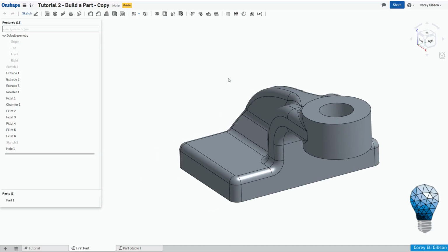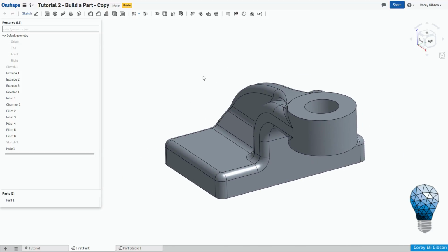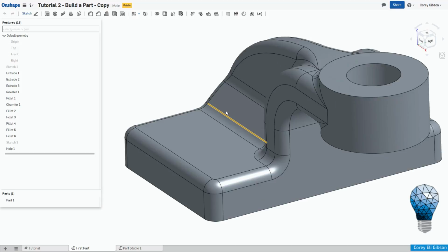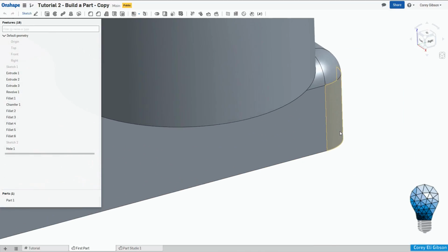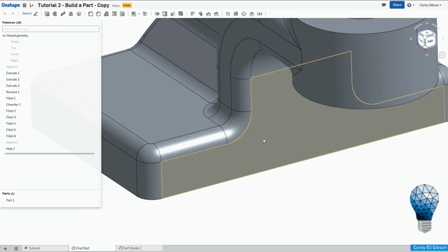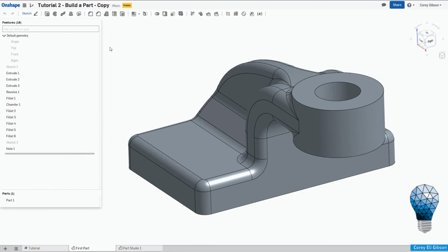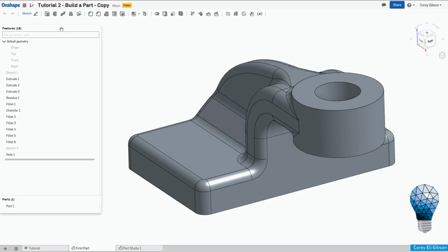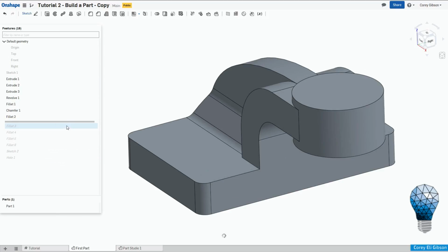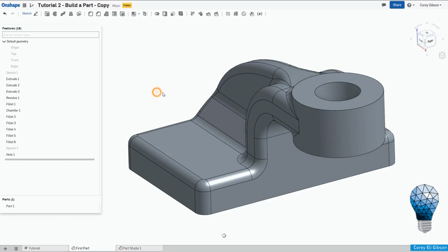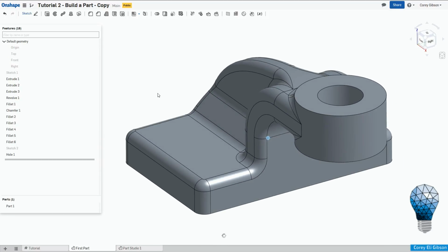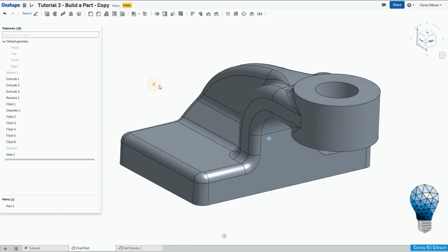If you want to pan, you hold down Control and right click, move it around, and then if you want to zoom, you just use the scroll wheel to zoom in and out. It zooms in on wherever your mouse cursor is, so if you want to zoom out and then zoom in on a particular piece of detail, it's pretty simple. Like I showed you before, you can roll back your tree there with your features in it, and then come back through and bring those features back in, just like most other good parametric modelling software.